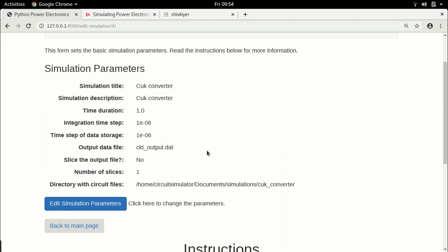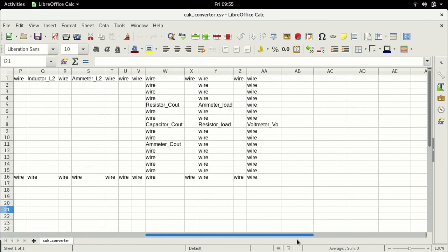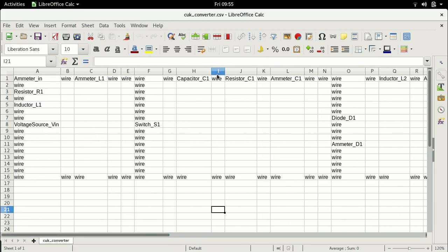So first thing we have to do is go back to the circuit, and I realized I made a mistake, or rather I didn't really make a mistake. I forgot to add one thing. We already talked about how the circuit is built. That is, we have two inductors, an input inductor and an output inductor, and we have a decoupling capacitor in the middle, and this decoupling capacitor plays the role of taking energy from the source and transferring energy to the output. So the only thing I forgot is we should measure the voltage across this as well.